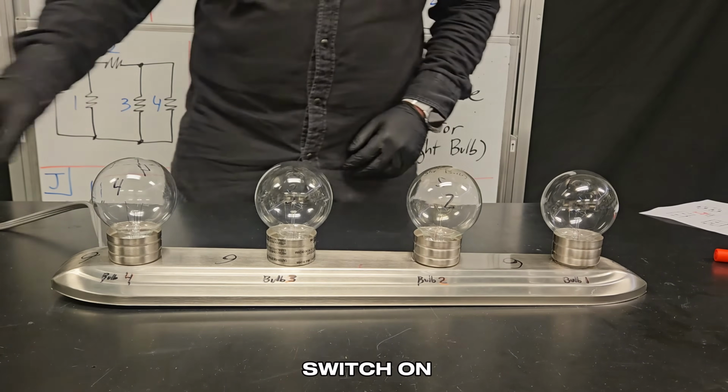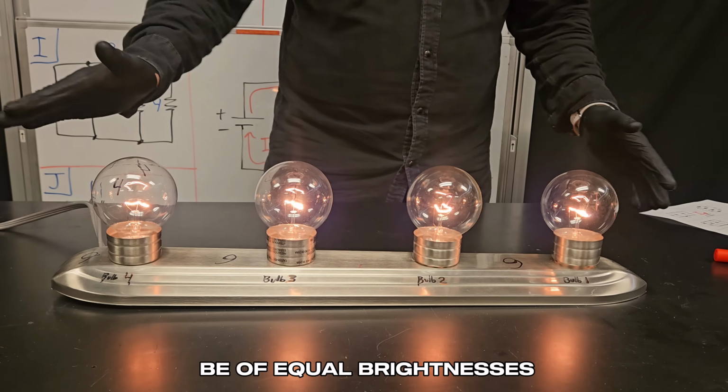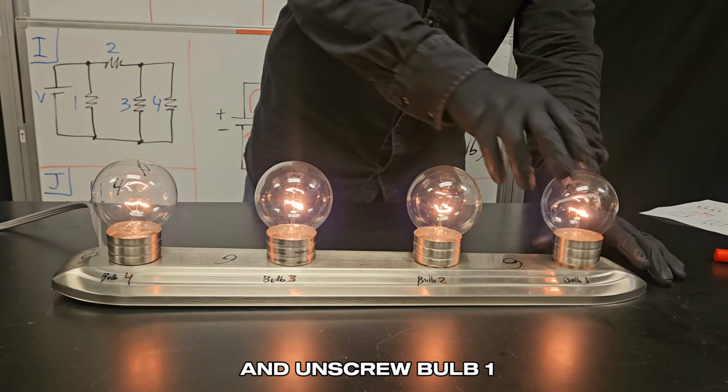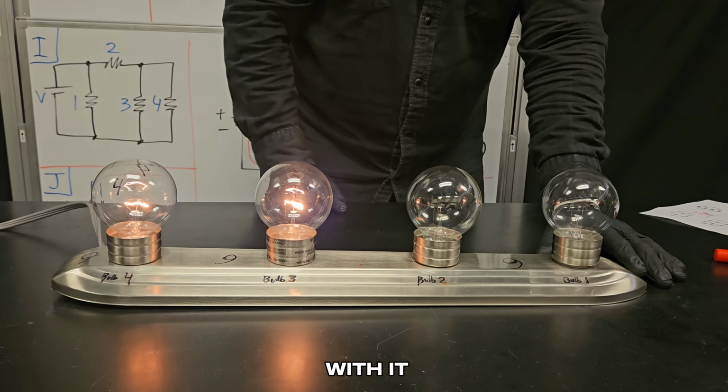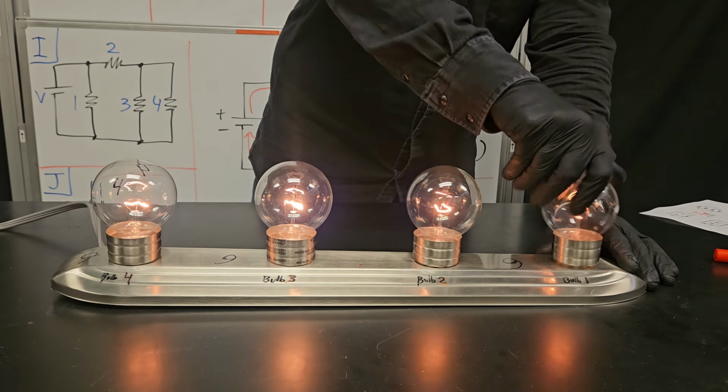Okay, so here we have station number 6. And when I turn the switch on, all of them are on. They all seem to be of equal brightnesses. I'm going to go ahead and unscrew bulb 1, and it looks like bulb 2 went out with it, but bulbs 3 and 4 stayed on.